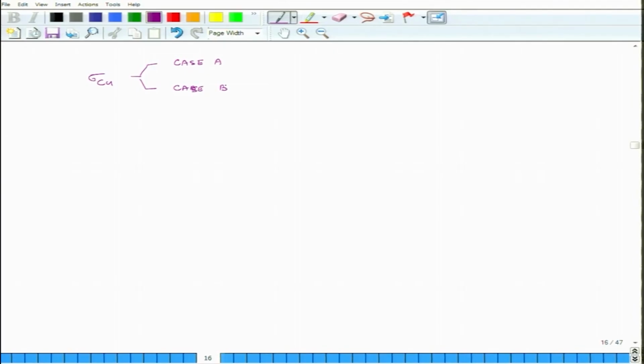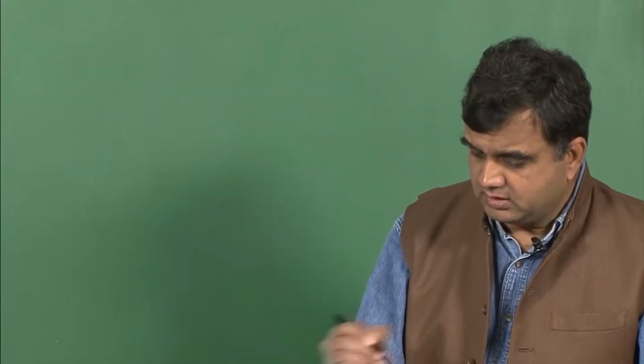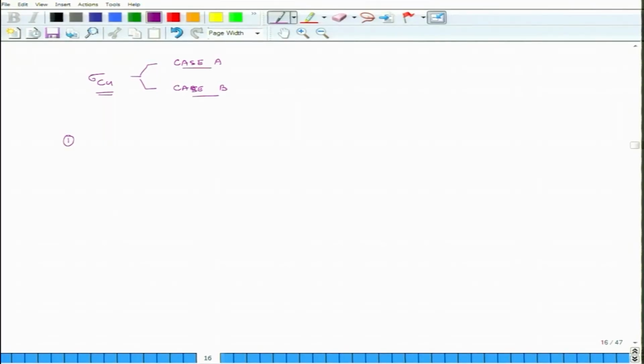They are the highest possible estimates based on some assumptions, but if those assumptions, which we will very quickly discuss now, are not necessarily true, then the calculation of sigma Cu based on case A and case B may be an upper limit, but real values will be somewhat lower. So, what are the assumptions which we assumed and we never explicitly stated? We had assumed one, that all the fibers were in exactly 0 degree direction. So, there was no misorientation of fibers.